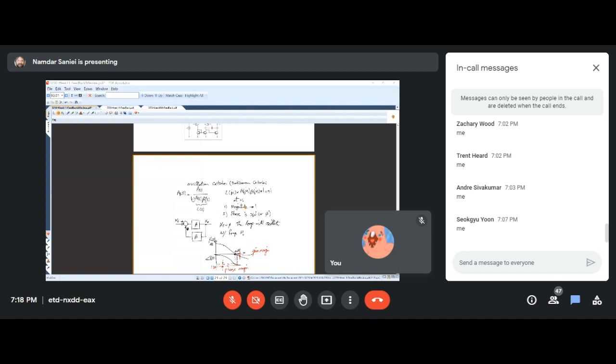If it is 1, and you can imagine that when we say A(s) beta(s), that means they are both dependent on frequency. So there is a place in frequency that this multiplication can have a value of 1.